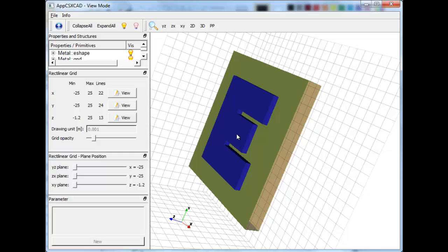Finally, a feed point is inserted into our structure. The feed point is drilled directly through the center of our structure. It is first drilled through the ground layer. It then is drilled through the substrate layer until it is in contact with the patch on top of the substrate layer. This procedure allows us to properly excite our ultra-wideband patch antenna.